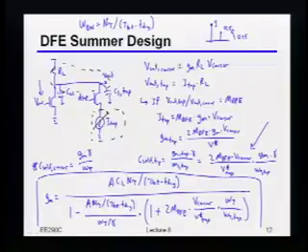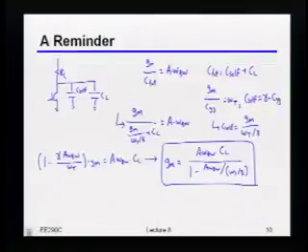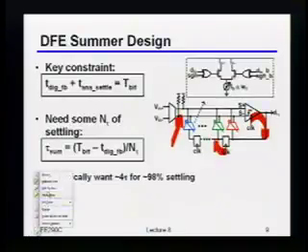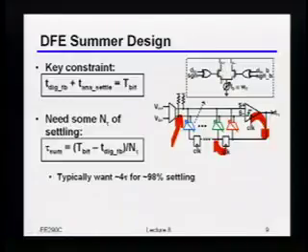So depending on the data pattern, your output impedance on a total... Great question. Actually I'll have to go back to this other picture to make that more clear. You're saying that each one of these switches could be flipped one way or the other. So I could have one data pattern where, let's say, I had 20 taps, where 19 of them are flipped one way and I'm just flipping one of them back and forth. That will be very different than having 19 of them flipped the other way and flipping one back and forth. You're absolutely right. That will indeed modulate the impedance on that node, and it'll cause nonlinearity.